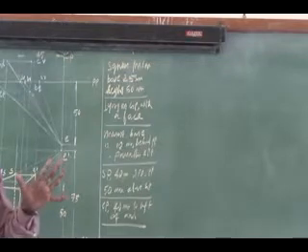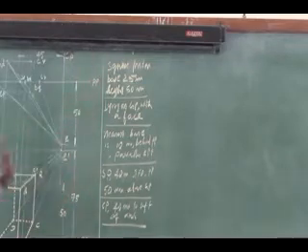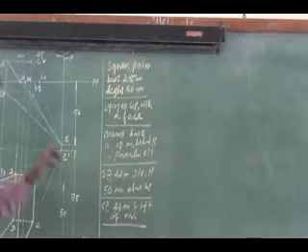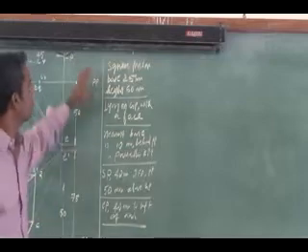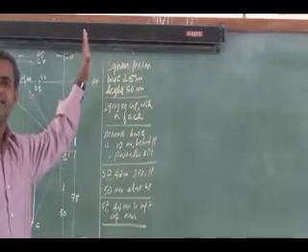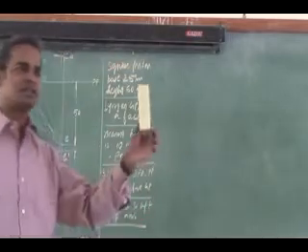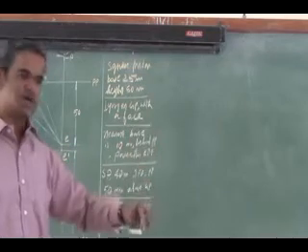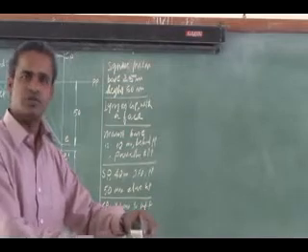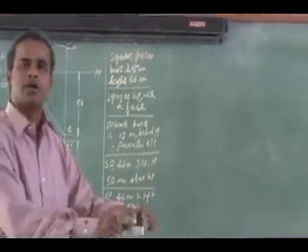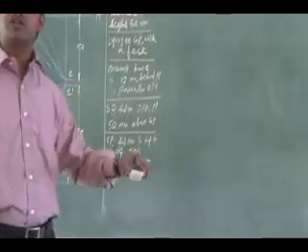Similar to the first problem, the center plane is to the left, similar to the very first problem. The station point in front of, above distance is given directly. What is the difference here? The solid's orientation. So far the solid was kept vertically like this. Now the solid is like this, so this is going to be the nearest base. It is lying on its face. The nearest base is 10 mm behind the picture plane, and it is parallel to the picture plane. That is the difference.